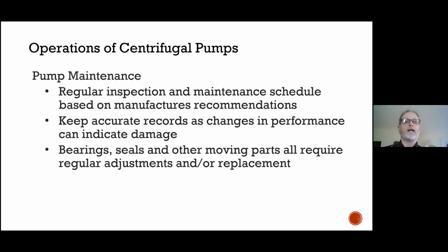As opposed to a regular bearing on its own raceway, which should be greased with the appropriate material. In other words, the grease should be approved for use in a water system, and it should be approved by that motor and/or pump manufacturer for use on those particular bearings.